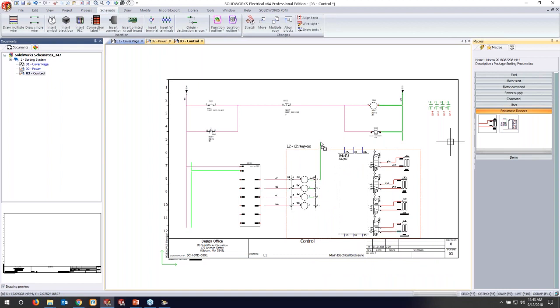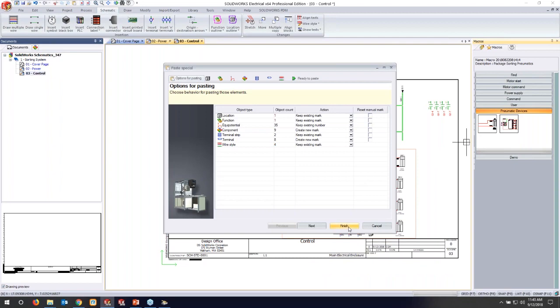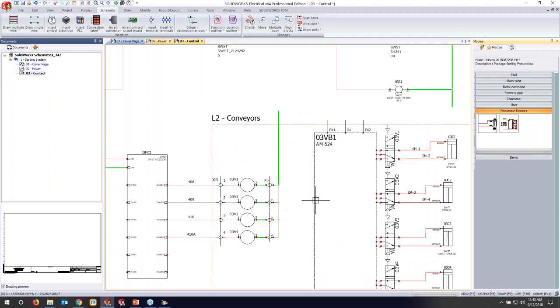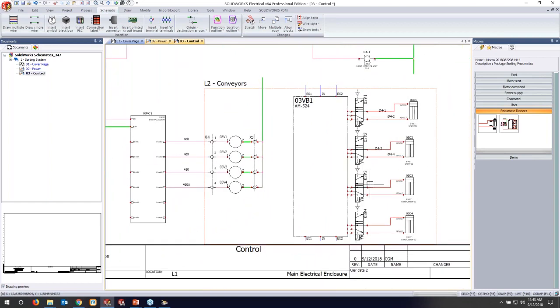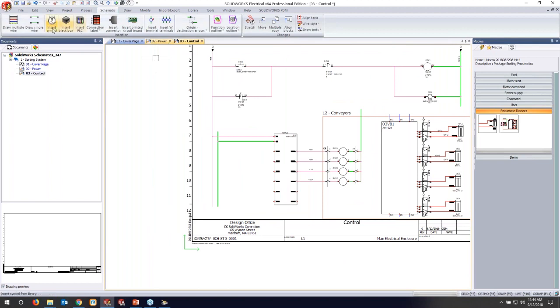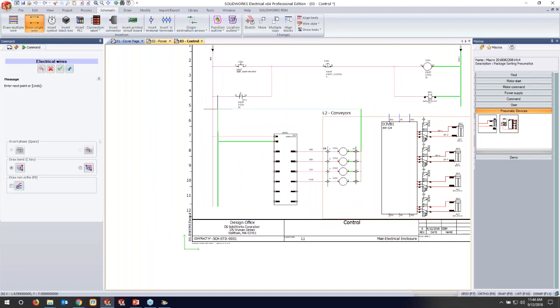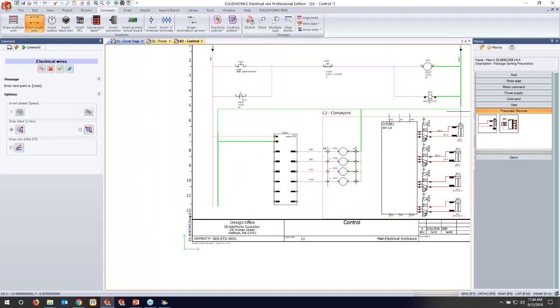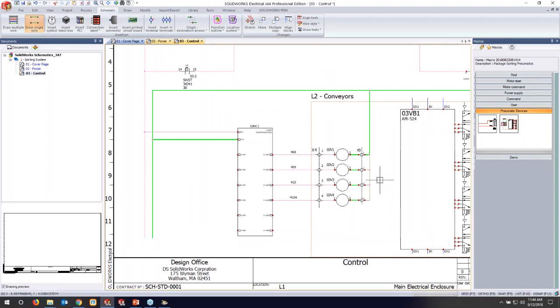And this is just to show you guys that you can do all sorts of connectivity and get stuff dropped in there with that. All right, so this is a pneumatic solenoid, bunch of pneumatic cylinders. So you can do pneumatics and hydraulics also, just so you're aware of it. Here's the coils for those pneumatic solenoids. And then I just have to connect up my ground wires and get those all connected up and together. You know, so if I come up, draw across everything, and now all of my ground wires are connected up. Okay, so those are all connected.